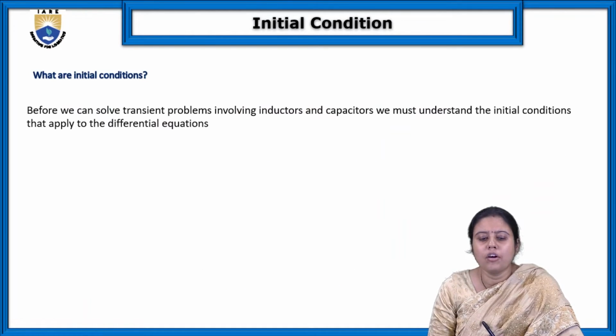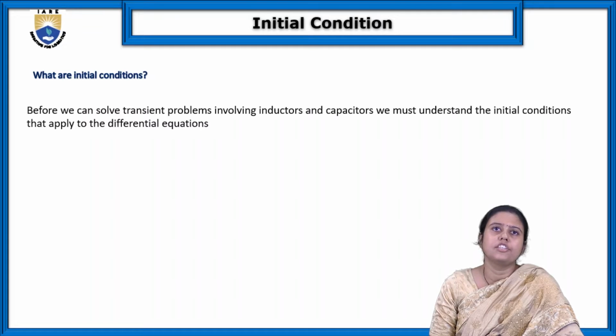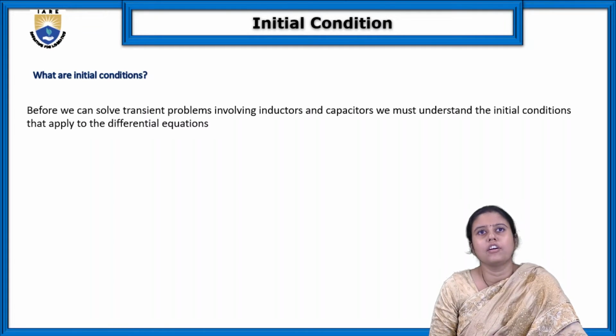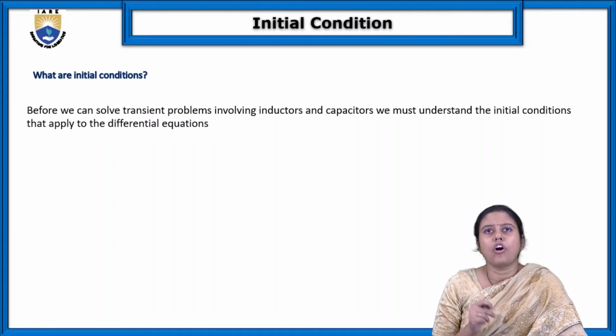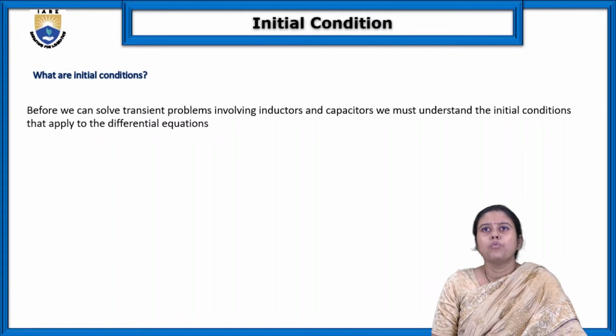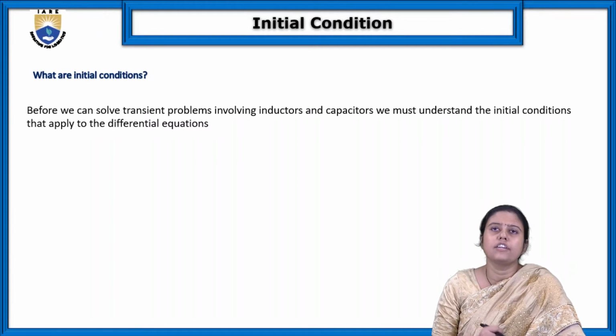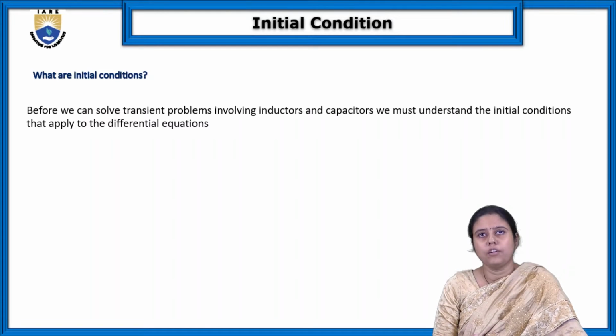Next important thing of this topic is the initial conditions. What are the initial conditions? Before we can solve any transient problems, we should know the initial conditions of the inductors and capacitors. We must understand what basically are the initial conditions of the differential equations.